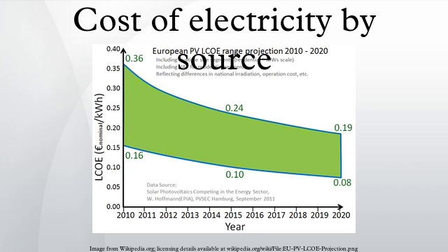All generating types are assumed to have the same 30-year cost recovery period, regardless of the expected lifetime of the plant. From the EIA report, the levelized cost shown for each utility-scale generation technology in the tables in this discussion are calculated based on a 30-year cost recovery period, using a real after-tax weighted average cost of capital of 6.6%. Incentives, tax credits, production mandates, etc. are discussed in the overall comprehensive EIA report, Annual Energy Outlook 2012.